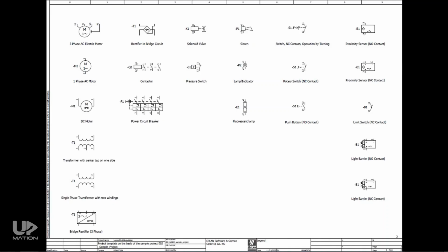Normally, the very first step to learn reading a wiring diagram is becoming familiar with the symbols of the equipment, and each wiring diagram is supposed to have a page or two for this purpose. This page is known as legend and abbreviation page.